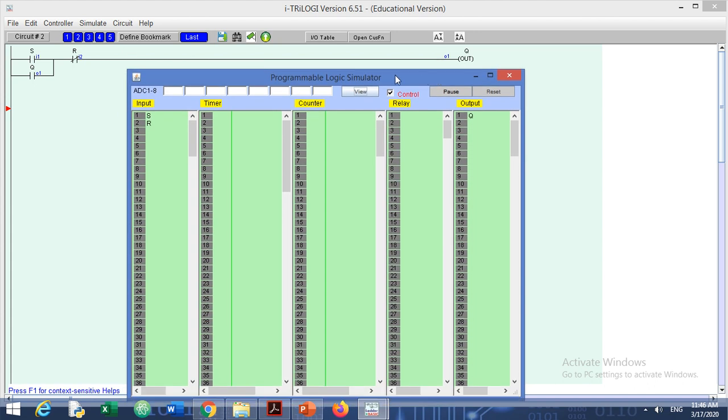So that is the difference between set and reset flip-flop. These kind of logics are used to start the motor and stop the motor. So you can imagine that there are two switches. By pressing one button you can start the motor and it remains in on state, whereas when you press the second button, that is a reset button, the motor goes off. So you don't have to push the button for a long time. It can be momentary.